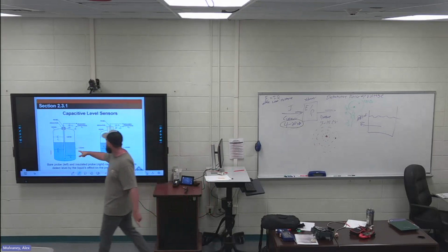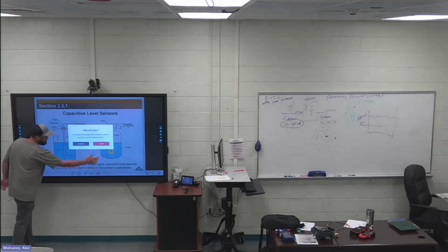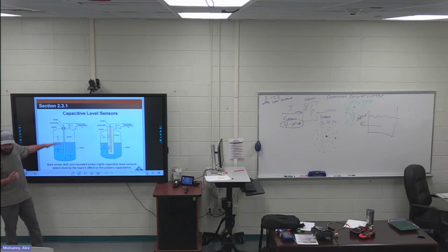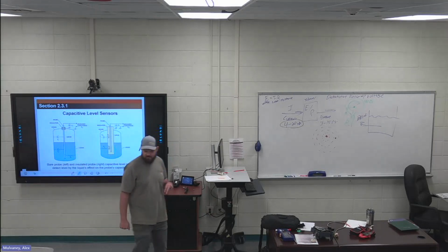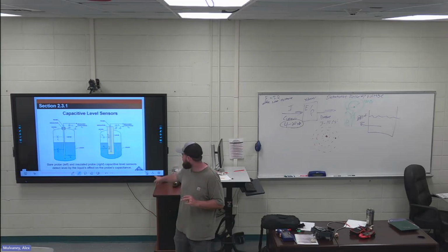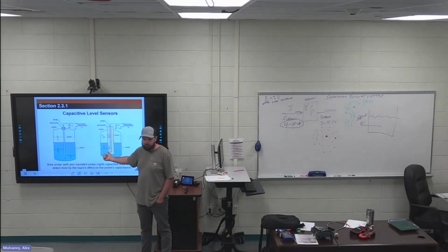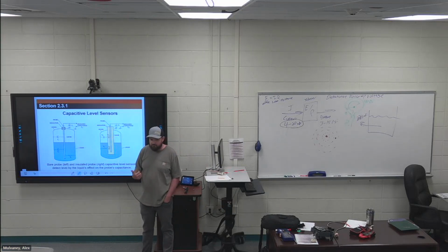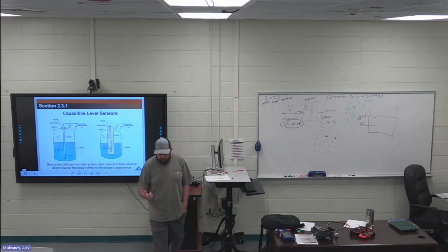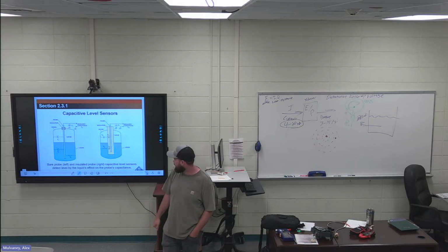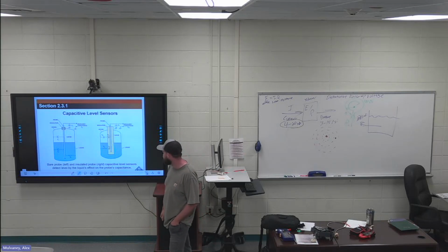And this is with a non-conductive liquid that you can use the tank walls with a metal probe. Non-conductive. So the dielectric is what's changing the capacitance to determine the level. The second one is if you have a conductive load or conductive material as your dielectric, you just have to insulate the probe. With what? Teflon. Yeah. Does that make sense? Turning your whole tank into a capacitor.